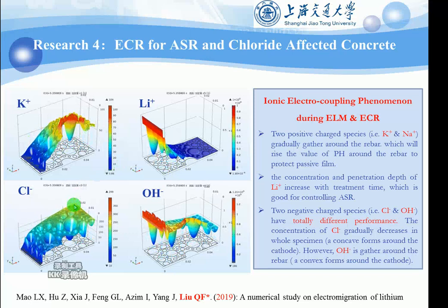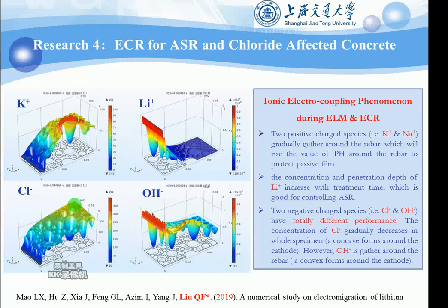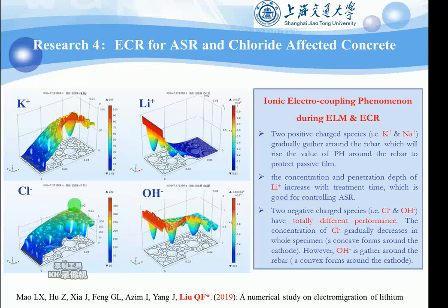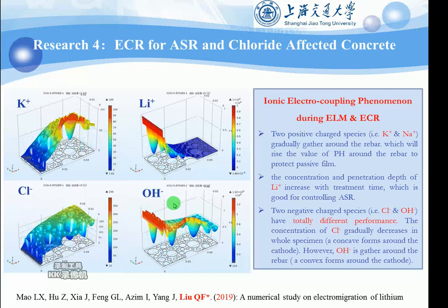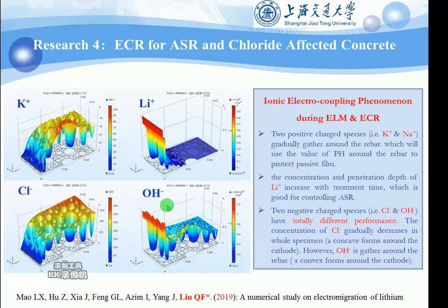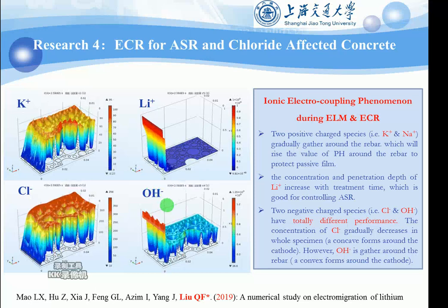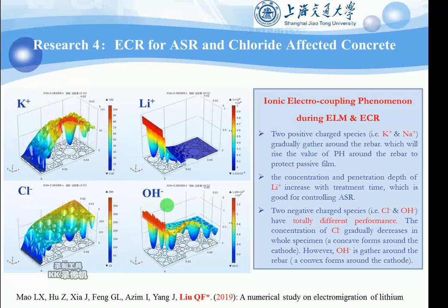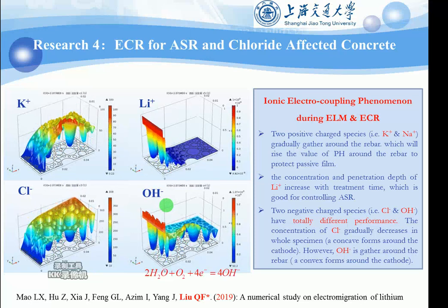The concentration of chloride gradually decreases in the whole specimen. However, hydroxide is gathered around the rebar. This is due to the reactions taking place at the steel cathode, which provides another flux for hydroxide.